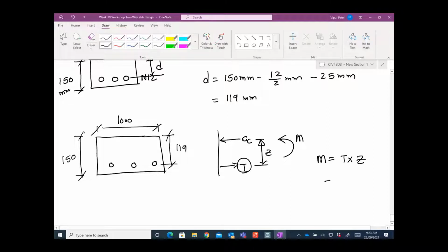And we have to make an assumption here to make Ku equal to 0.36, ductile. We said that the lever arm would be 0.90. This is the assumption, and this assumption works for every beam that you want to design for ductility. So we assume this one, and there is nothing wrong in these assumptions, right? This is a very conservative assumption. It always works in the slab.